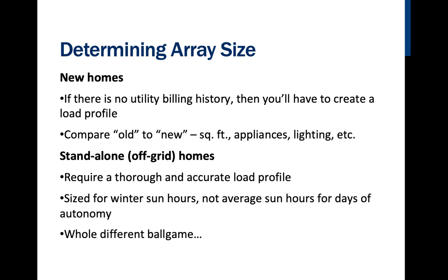Standalone system. For a standalone system, we're going to make a highly accurate daily load profile. So we're going to make an inventory of everything electrical that we need to run on a daily basis. What is the object? What is the consumption in watts? How long does it run? And come up with a watt-hour estimate of our consumption on a daily basis.